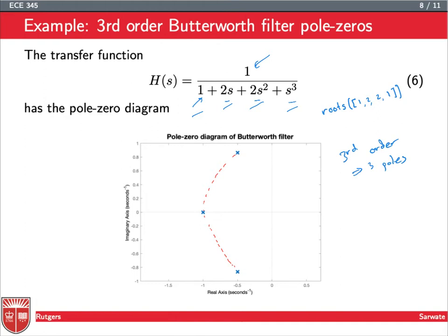Okay, so then the question is, what does the surface look like that you get out of this Butterworth filter? Here, there are only the poles pulling up the sheet, and we have no zeros pinning it down. So we're going to get some tent poles in there, in particular this conjugate pair, and we have something in the middle. That thing in the middle might help when the sheet starts to sag between these two poles here. If you think about sticking up two tent poles, there's a little bit of a curve downward, but this pole might help pull it back up.